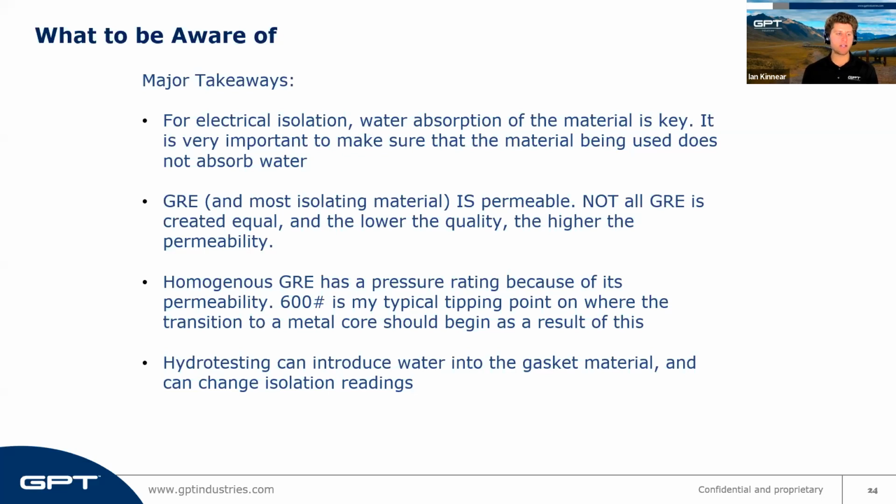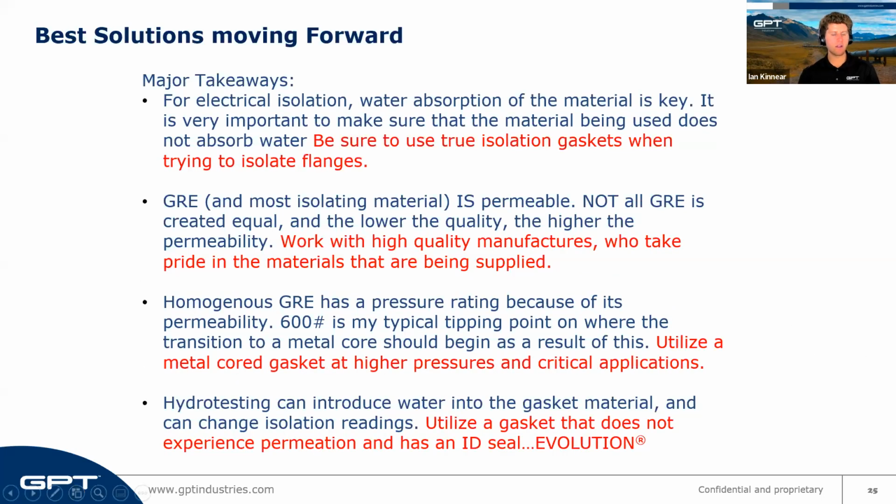And then lastly, hydro testing can introduce water into the gasket material and can change isolation readings. There are some solutions to this. We can talk about that, and it's just something to be aware of. So those are the takeaways.